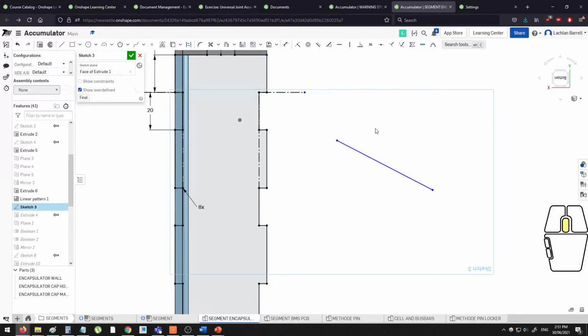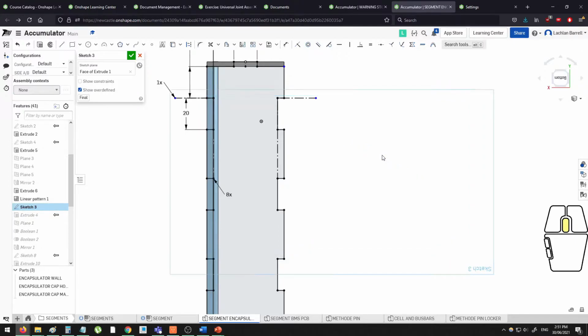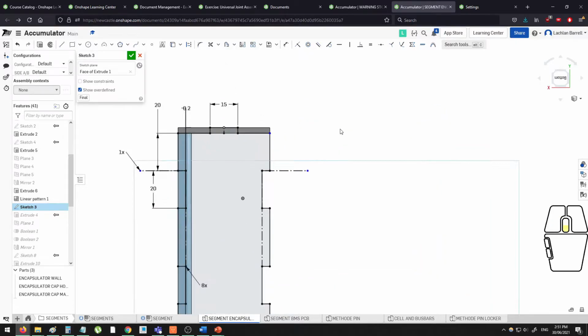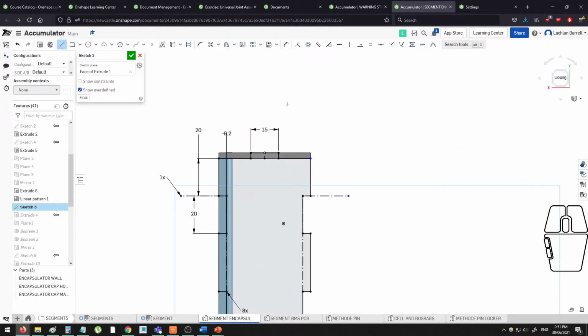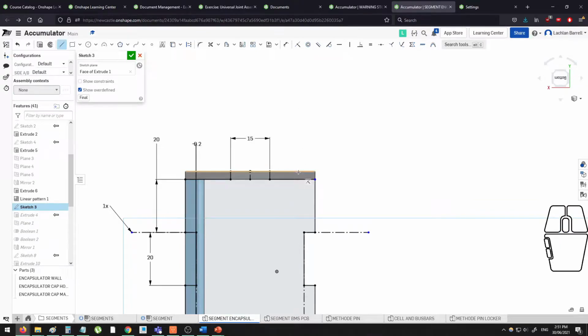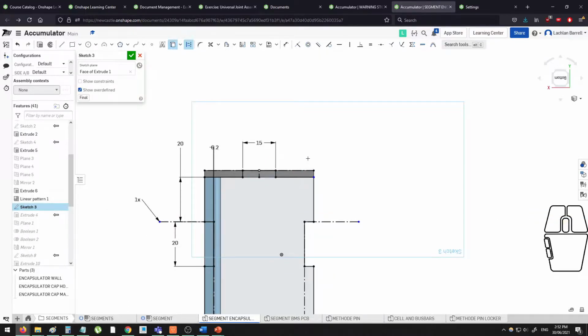The next tip relates to the Use tool, which is this one here. Depending on what environment you're in, sometimes when you're doing a sketch in Onshape, it will or won't let you snap to geometry outside of your sketch. You can see right here, I'm in the same part studio, so it will let me. Sometimes it won't though. That being said, it's potentially useful for me to grab this entire line, either as construction geometry or as real geometry. For now, I'm just going to use construction geometry. I can click that line and you can see that line then gets projected into my sketch as construction geometry.